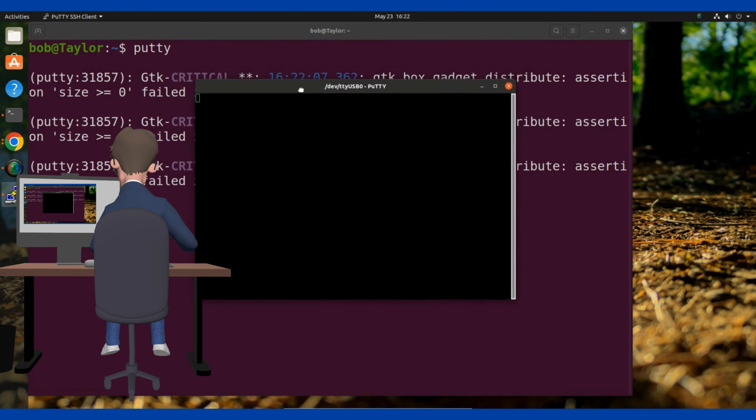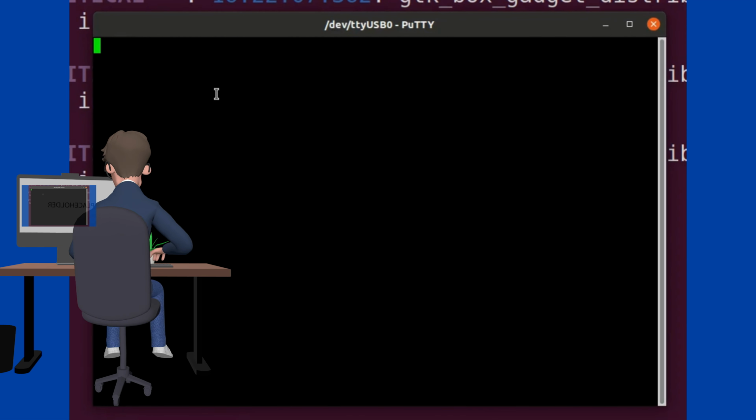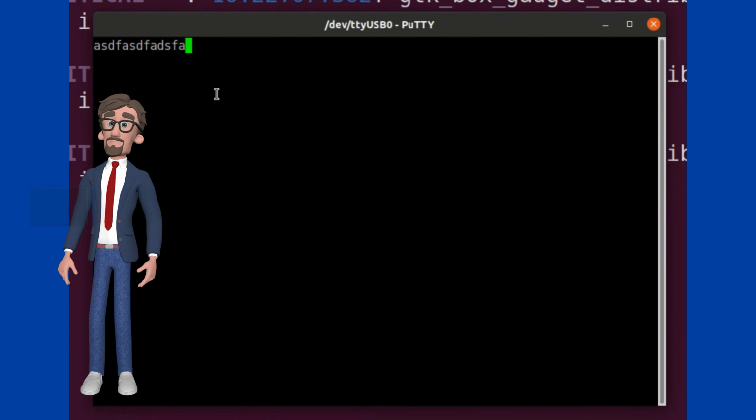I am going to make this a bit easier for you to see on your screen. That's about right. Now when you type in a character from your keyboard, a data signal is sent to the converter transmit pin and loops back into the converter receive pin. This data is then echoed back onto your terminal screen. This concludes our loopback test and ensures that our future Flutter app will work.